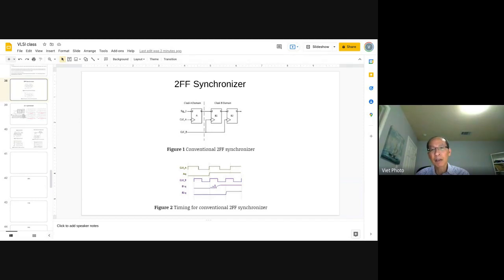If it fails, everything fails. So usually for the flop, they will use 5 sigma or 6 sigma. In the old days it was 6 sigma, but now they use only 5 sigma. The reason is that the number of cells is too high. If you use 6 sigma, it's too much data to collect.